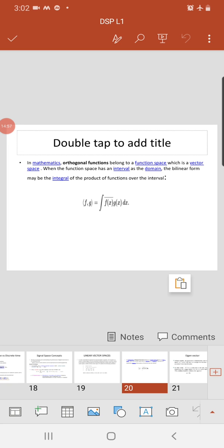Suppose we have a set of M signal waveforms, and we want to use these waveforms to transmit over a communication channel. Then we find a set of N, with M greater than or equal to N, orthonormal basis waveforms for our signal space, from which we can construct all of our M signal waveforms. Orthonormal in this case implies that the set of basis signals are orthogonal. So we represent each signal waveform by its vector coefficients, knowing what the basis functions are to which they correspond. So we similarly think of the point in n-dimensional space.